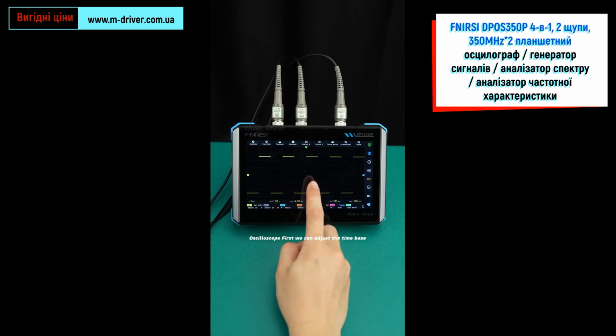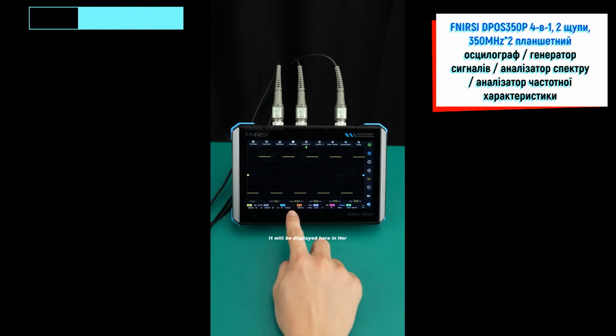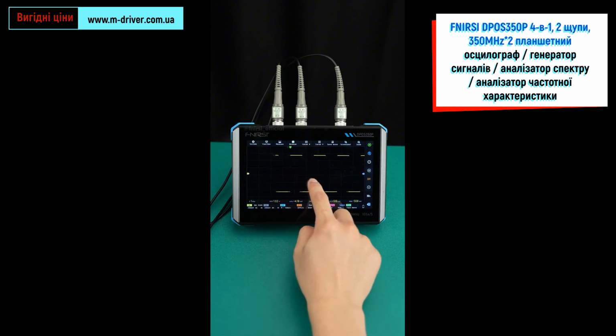Oscilloscope. First we can adjust the time base. Click on the left to zoom out, click on the right to zoom in on the timing. The current time base will be displayed here in HOR. We slide left and right on the screen, and the waveform can be offset left and right.